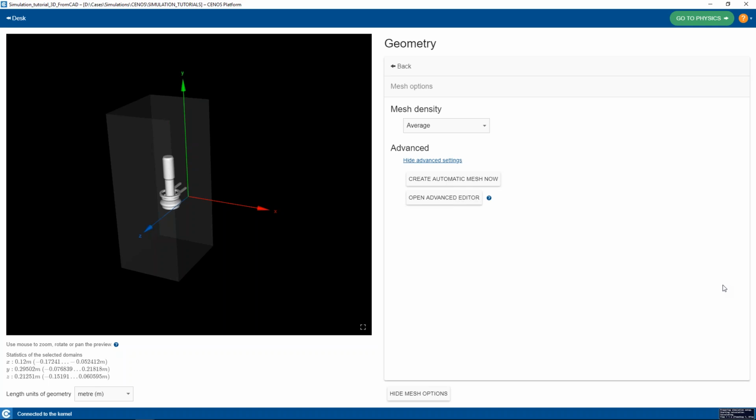Basically, the calculation time directly depends on the element count. So whatever mesh refinement you are creating in your mesh, the main goal would be to decrease the element count of the simulation, because that is basically the only characteristic that will impact the calculation time.